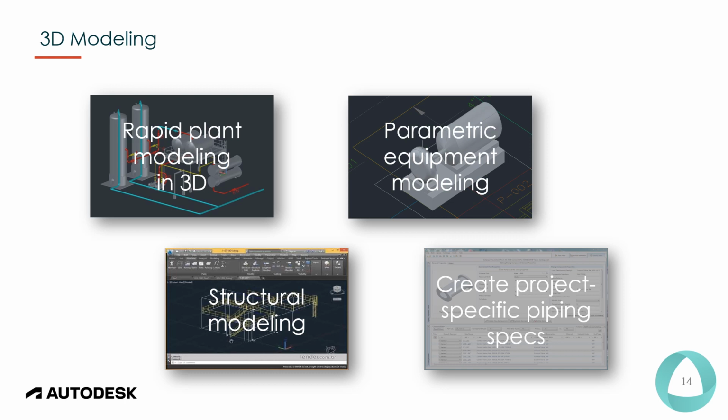For any intricate equipment, you can use Fusion and Inventor as well, which integrates with Plant. Then on the structural modeling, you have your structures, stairs, ladders, and railing commands to design your structures in Plant using your international standards as well as SANS standards. For any detailing or connection modeling, we would recommend using Revit or Advanced Steel, which also nicely integrates with Plant.